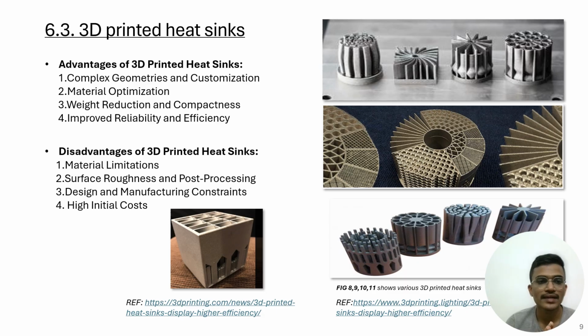But what are the disadvantages? Material limitation, as not all materials can be used for 3D printing. Then comes surface roughness and post processing. As we know, 3D printing sometimes requires post processing to improve its surface finish. Then comes design and manufacturing constraints and very high initial cost.